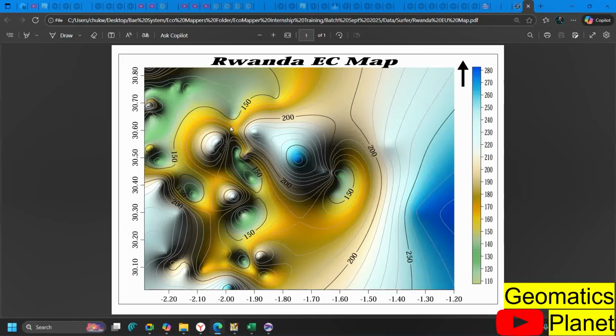So we'll dive deeper into it, and I can show you how to create a geological map, add points to it, like if I want to put Musanze, Muhanga, and the rest of them, I'm going to label it for you, put it as a point style. I will bring point, line, and polygon for you, and we overlay it here. Assume you want to simulate the flood, or you want to see the flood. Where is the flood affecting the road? Where is it affecting building footprints? And the rest of them. So we are going to get that done here. But as you can see here, this is the output of this particular file format we have created.